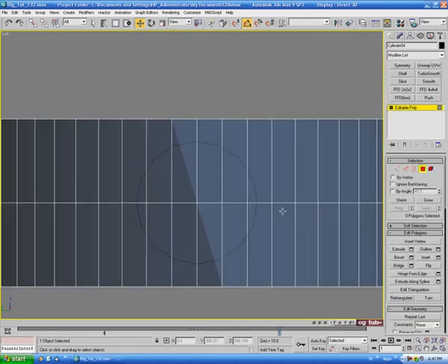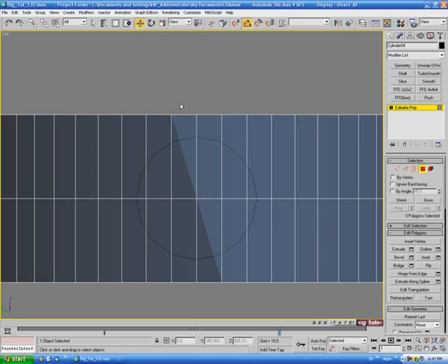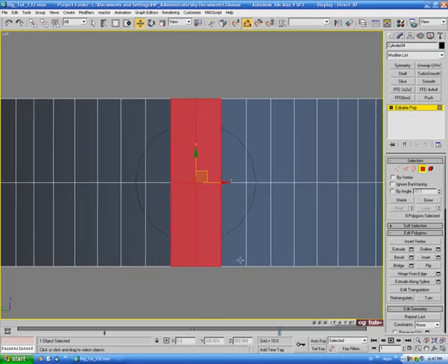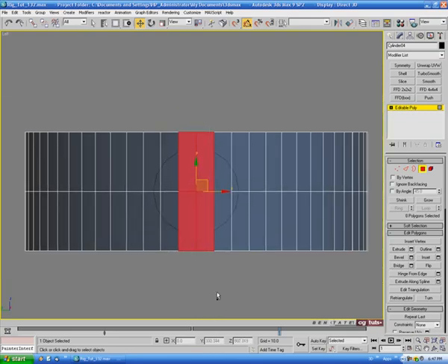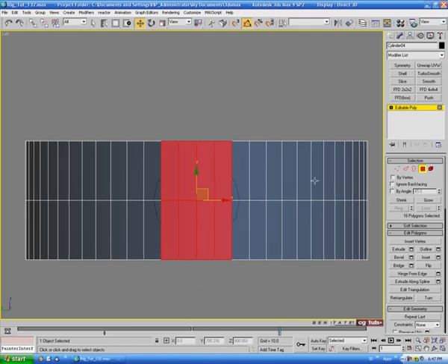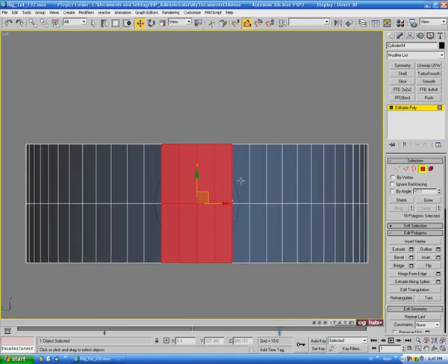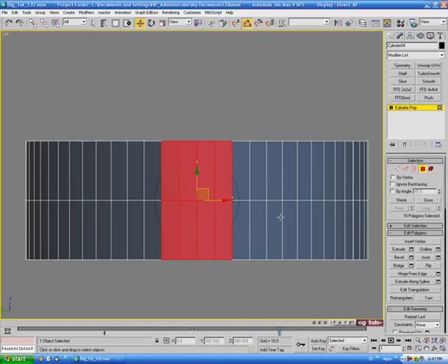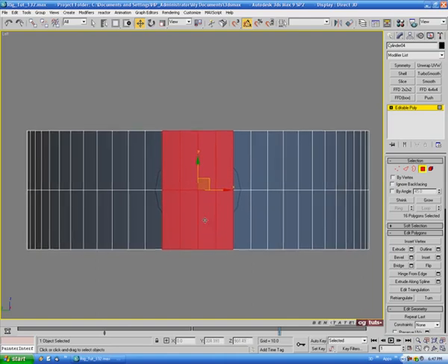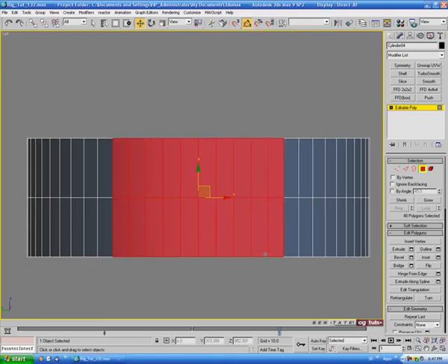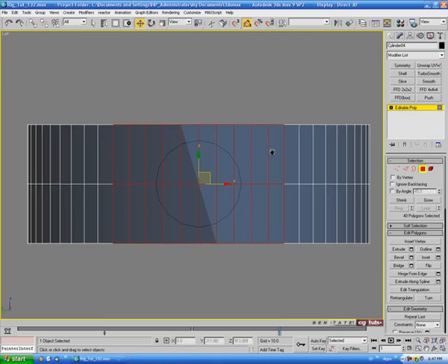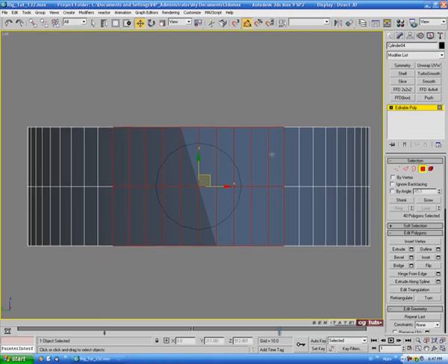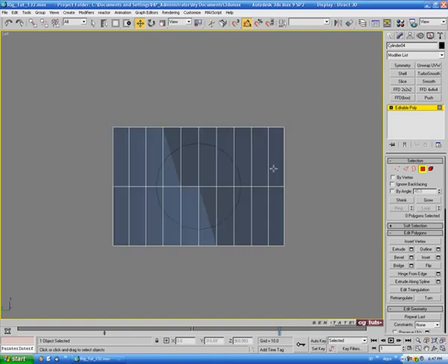Let's go into polygon. I'm just going to grab the 4 center pulleys there, and we're just going to figure out how many of these we need. We need to have 6 holes around it. Alright, we have 60 sides on the cylinder, so we're just going to select a selection of 10 polygons here, 10 wide. Okay, so like that. Okay, so just make sure you have 10 across. And with those selected, I'm going to do Control I again and delete.